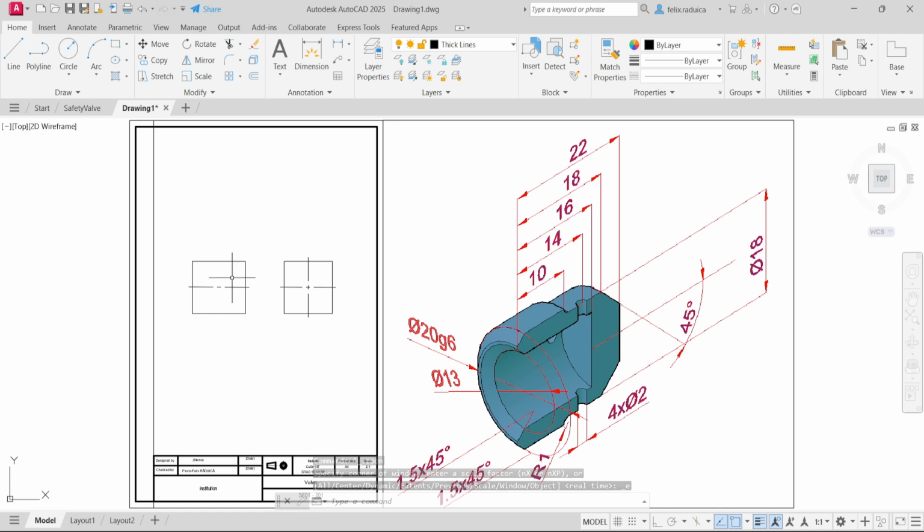I place the axis lines. For the section view here, we have only one vertical axis line, which is in the middle. And on the side view here, we have one horizontal and one vertical axis, which are also in the middle of the rectangle vertically and horizontally. When you look at the part from the side, this side, you have 4 circles to draw.